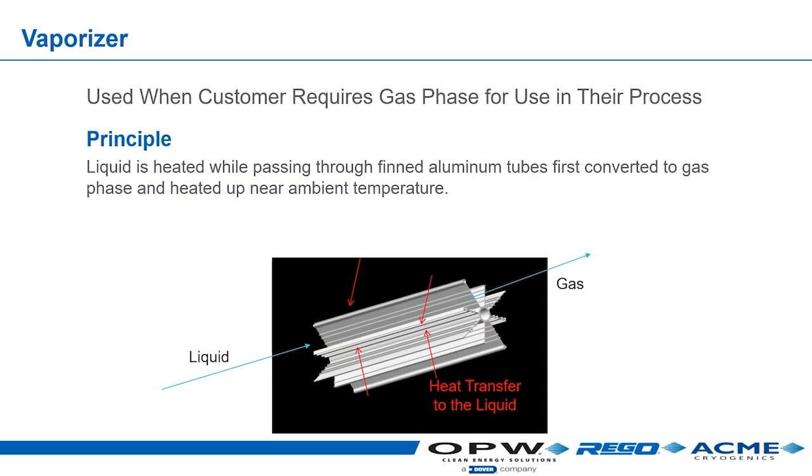And that's called an ambient vaporizer, meaning ambient, it's just the sun hitting it, and there's no external force helping it. And the biggest thing with the vaporizers is sizing them correctly based on someone's flow rate, because it determines how tall the vaporizers are and how many you need. You always want to make sure you have more than enough vaporizer, so the customer's in the proper supply with the right pressure and the right flow rate.